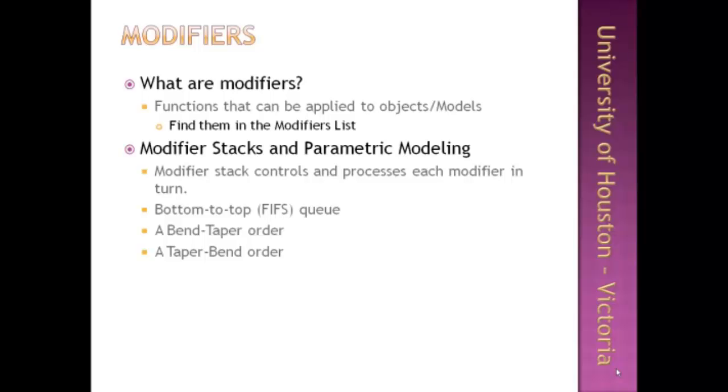Another thing to notice is that the order of the modifier operations is not chronological. It doesn't matter how early or how late you apply your modifiers to the stack, they will still be ordered and processed from the bottom to top. You can reorder your modifiers, moving them up and down within the stack to get the desired result.